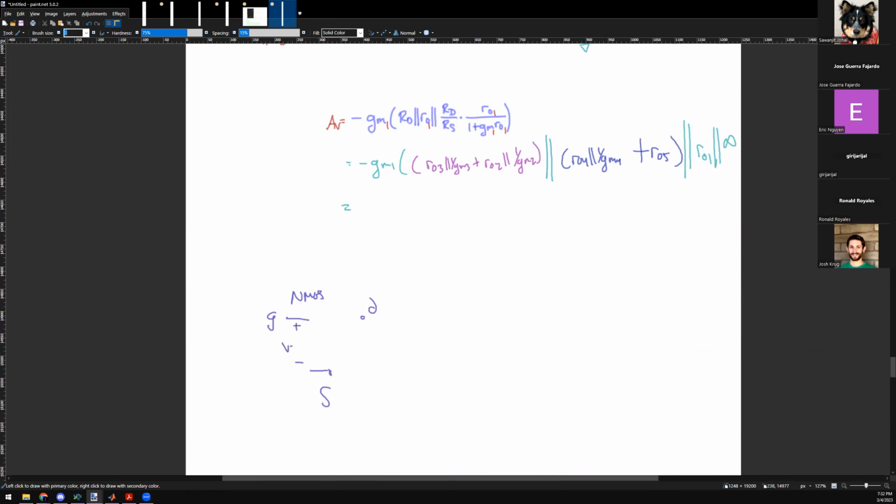Okay, but I call this VGS. And then there are two components from the drain. There's a resistor, and I call it R naught. And there's also a current source that points which way? Not down, from where to where? Drain to source, and I label it gm VGS. Good. If I switch the N to a P, it's the same thing.